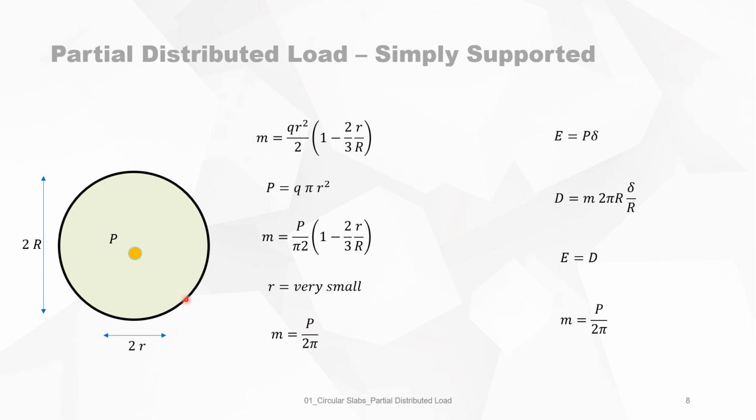So it means that because there are so many yield lines, when every yield line is yielding, then the resistance, if I can call it like that, is proportional to something squared. So it's proportional to a surface. And that's why the bending moment is also proportional to r squared. So that's why those two cancel each other out. But the best explanation is that the work done by the internal forces is independent of the radius. That's why the bending moment is independent of the radius.